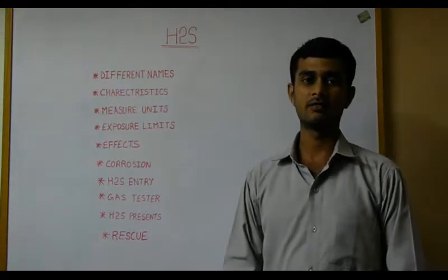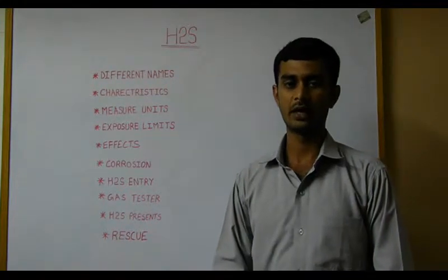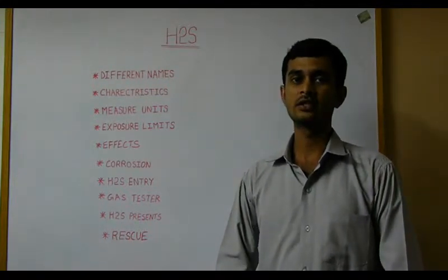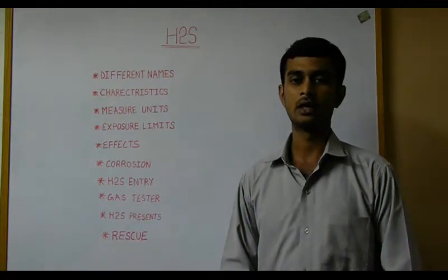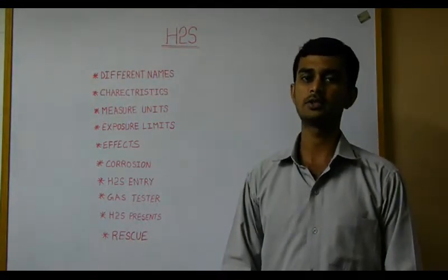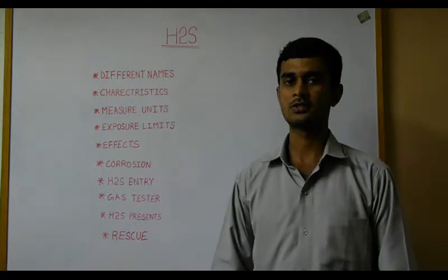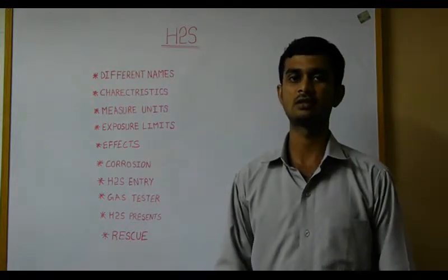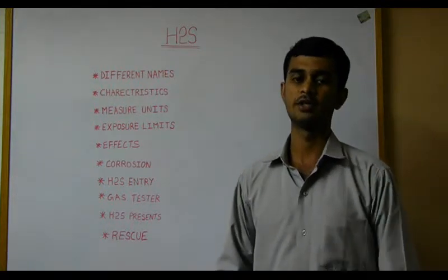Characteristics of hydrogen sulphide gas. This gas is colorless, so not visible to our naked eyes. This gas is odorless in higher concentrations. This gas has a corrosive nature and is 20% heavier than air, so deposition of this gas occurs in lower areas like pits, ducts, walls, excavations, trenches, etc. People working in this kind of areas should be aware of H2S.